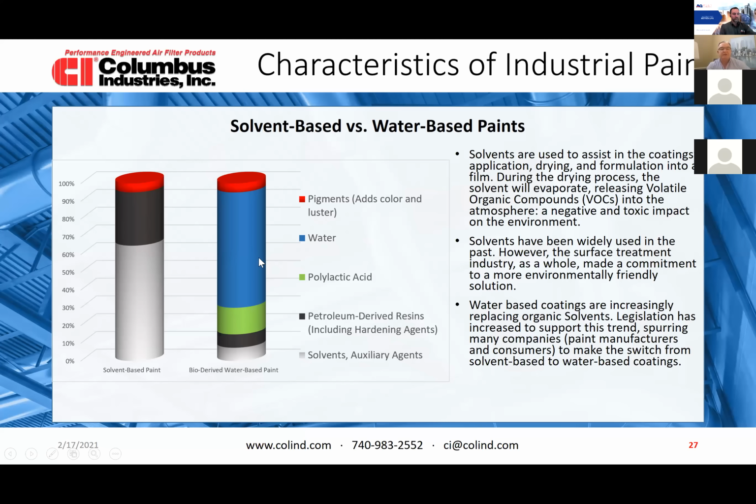So by moving here, there was an immense reduction in these things. CO2, which used to be this portion here, was reduced by up to 60% by moving to the waterborne. The VOC in the paint, or the solvents: by moving to the waterborne, you don't need as much solvent. You are reducing your VOCs by 80%.